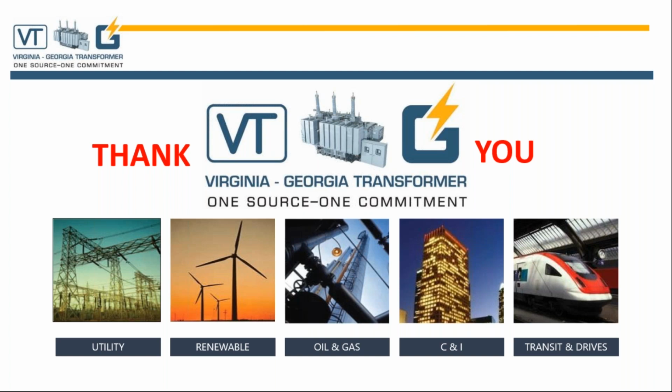Basically the problem comes down to increasing the excitation of the transformer. That's what reverse power is doing. The tertiary windings are used in transformers really for harmonic stabilization, like you said, Paolo, on YY or auto transformers. So just putting a delta in a transformer, thinking about the reverse power and saying, okay, let's put a tertiary winding so it's going to help, is not really going to help the situation, because the root of the problem is the injection of the energy back into the transformer.